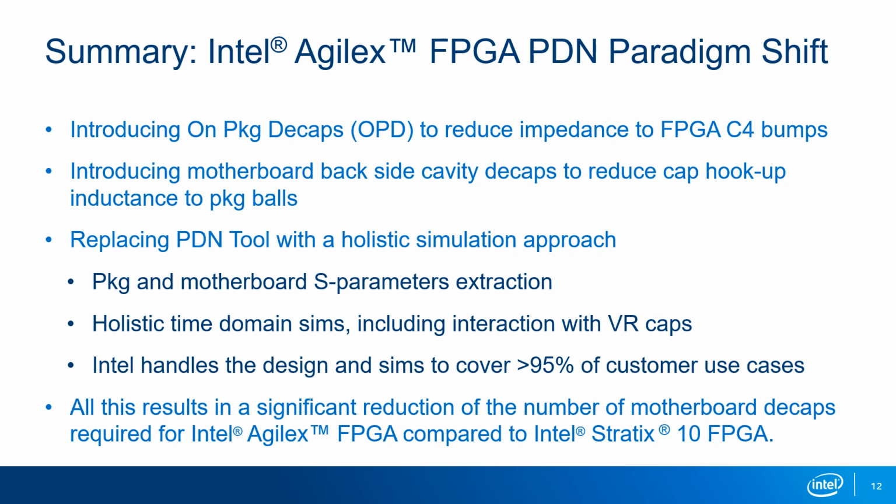So in summary, with the on-package decoupling caps, we've significantly reduced the number of motherboard backside cavity capacitors. We've also performed a more holistic simulation approach, which replaces the traditional PDN tool. We've performed simulations that cover over 95% of customer use cases. By referring to a static table, you'll be able to easily determine the number of motherboard capacitors and their values to ensure that you deliver clean power to the Agilex device. All of these improvements result in a significant reduction of the number of motherboard decoupling caps for the Agilex devices when compared to the Stratix 10.